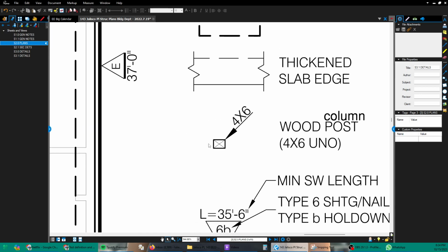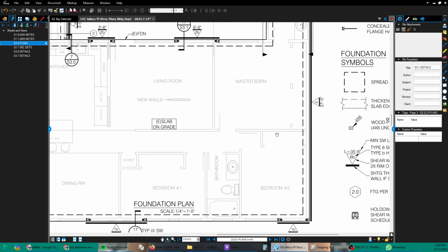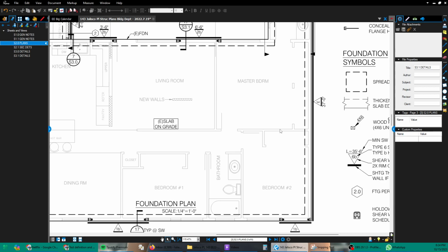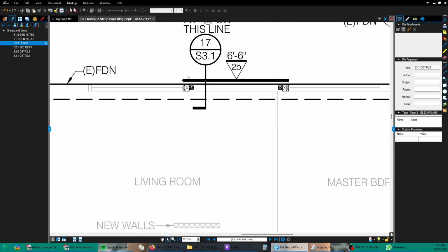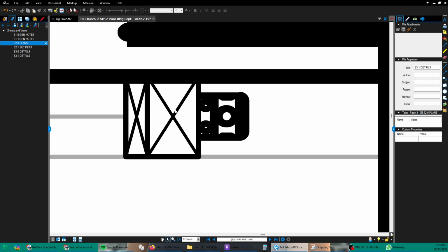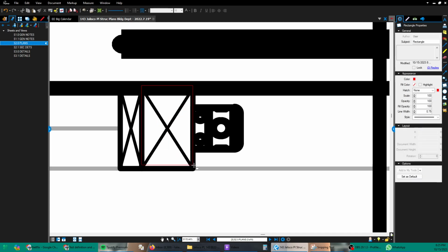So here's the cross section of the post. Because when we look at a plan view, we are looking at a view that is cut at knee level of the level we're standing on, looking down. That means that if there's a column, this shear wall end post is also a column. Our view is cutting right through that column. We look at the cross section and we see its rectangular cross section. This is a 4x6. That's why it appears longer in one direction than another.